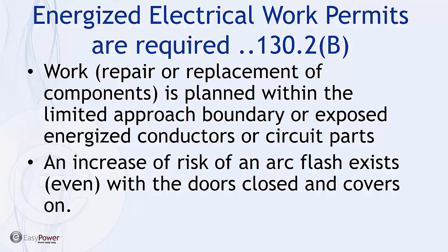So many of us initially thought that hot work permits were just a necessary piece of paperwork that's required by regulations. And while it may appear that way, the original intent and purpose of a hot work permit is to provide a standard procedure to complete the necessary work in the area of an elevated hazard and to do it safely. Frequently, that procedure may include specific steps to temporarily lower the incident energy, complete the work, and then restore the system to a normal configuration.